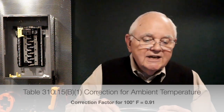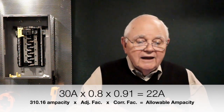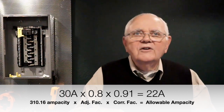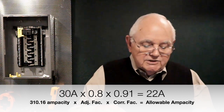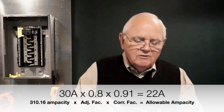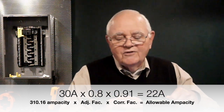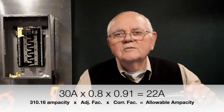So now I have to take the 24 times 0.91, and gosh, what do you come up with on that one? You'll have to figure that out. About 91% of 24, right? So the amount of allowable ampacity in my conductors, good homework problem for you, right? So the amount of allowable ampacity decreases even more.